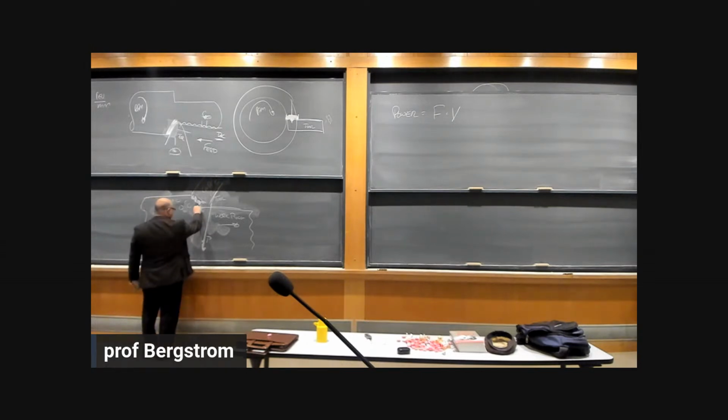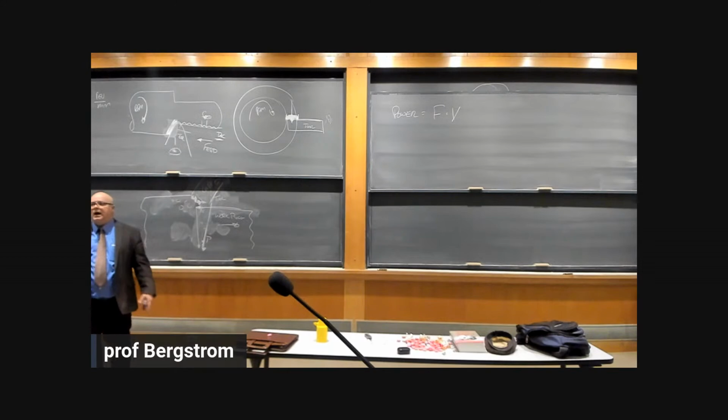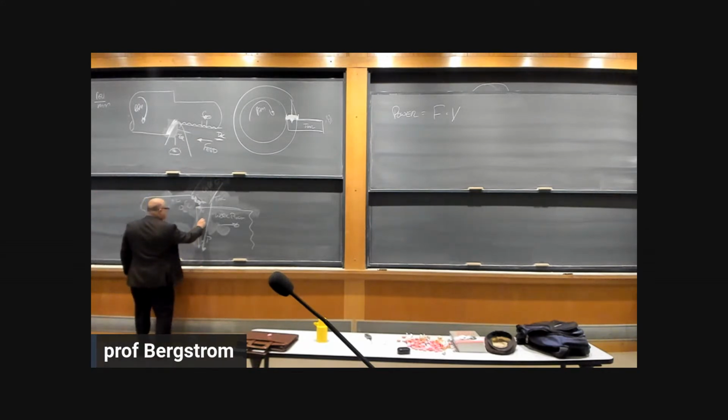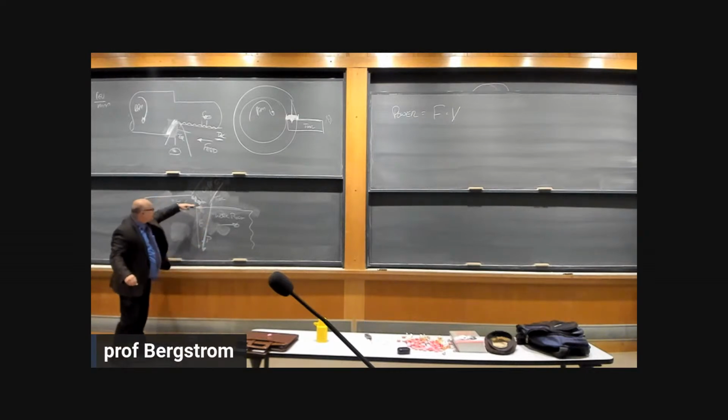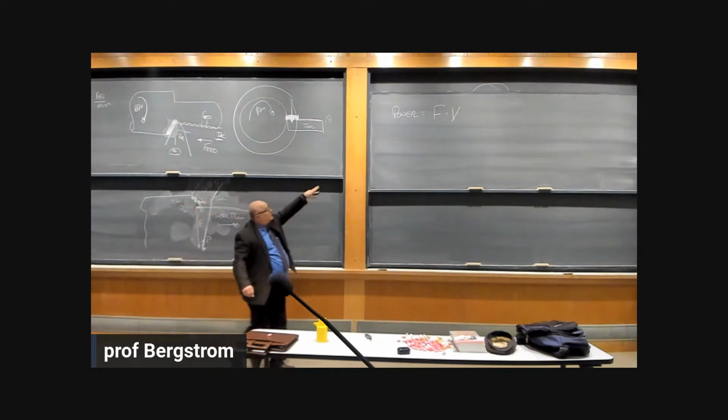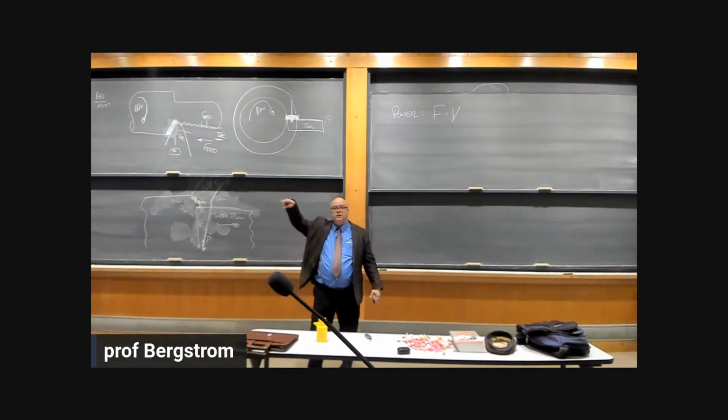And we can have a thrust force. That thrust force is going to come from the servos to the X, Y, and Z direction of the tool motor, moving the stuff around. And we'll call this FT, the thrust force. So we've got a cutting force that lines up here. And we know that this times velocity equals the power that we measure at the spindle.